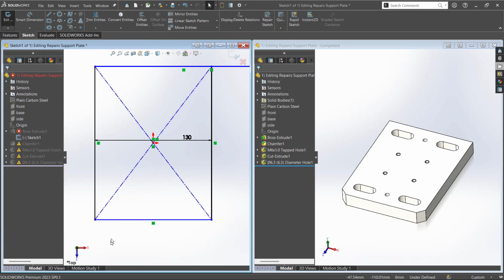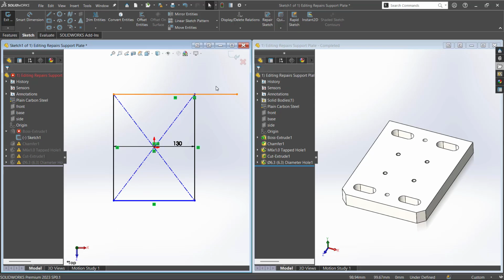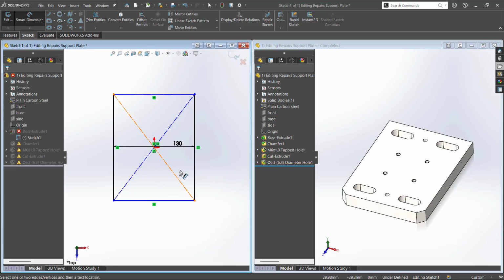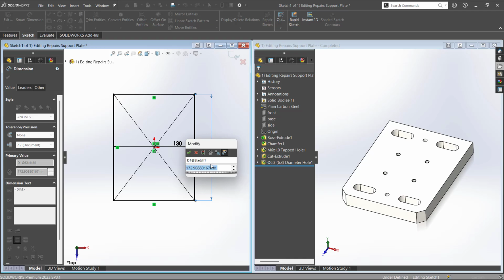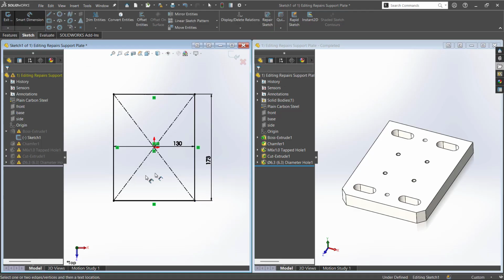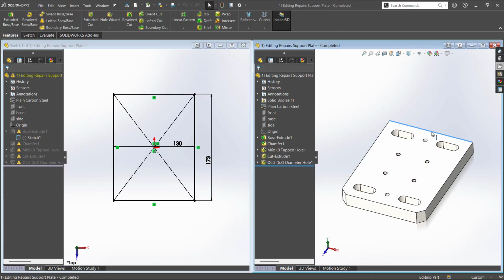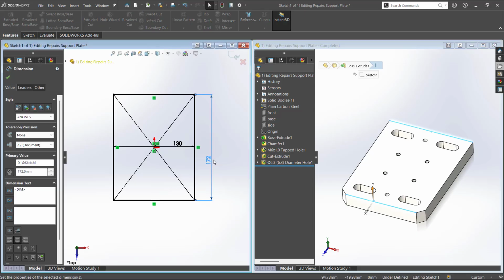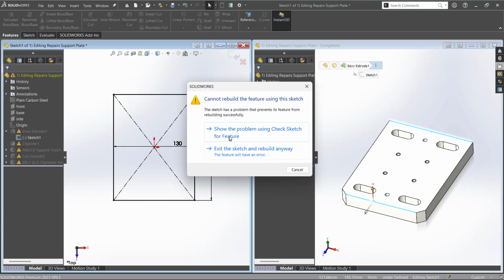So I could see there is an extension here, right? I can simply remove this, and there's no dimension defined for this. What I can do is let me just approximately measure. It shows 172.90. It might be 173. Let me just assign it at the moment. Just to make sure whether I'm right or not, I can use a shortcut. Hold the control, select these two edges, and automatically it shows the value here. Now the dimension is 172. In short, it should be 172. Right? Yep. I'm done with this.